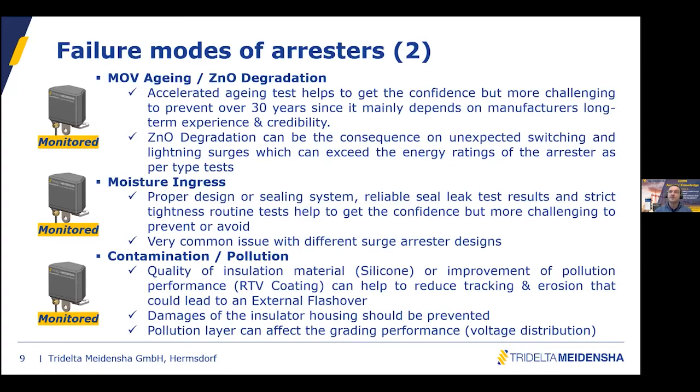We have seen from our field experience that moisture ingress is a very typical failure for surge arresters, whatever design you are using, even if it's a directly molded cage design or a hollow core porcelain or hollow core polymer. So it's a very common issue, and you can assess the surface current on the block in order to give you reliable, meaningful information. This is the second point.